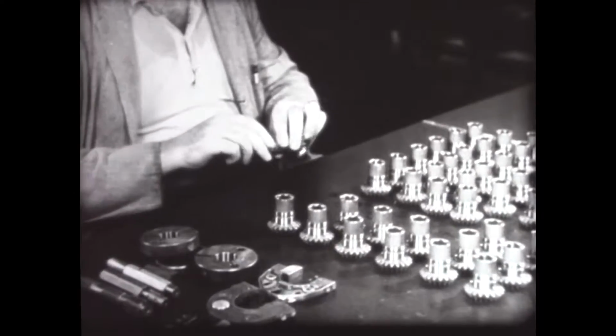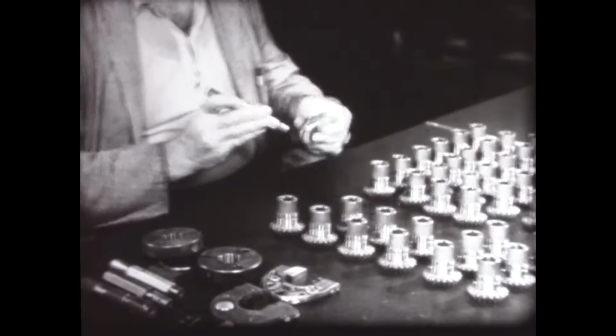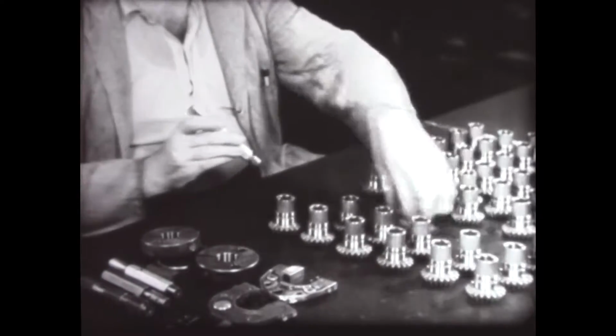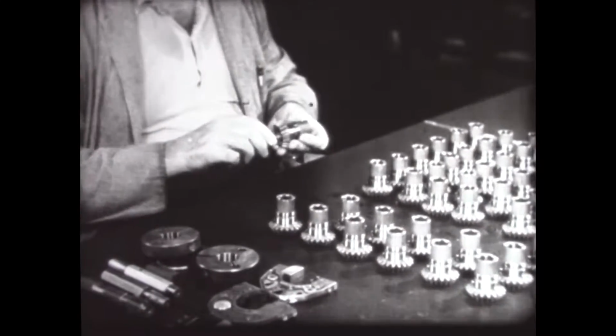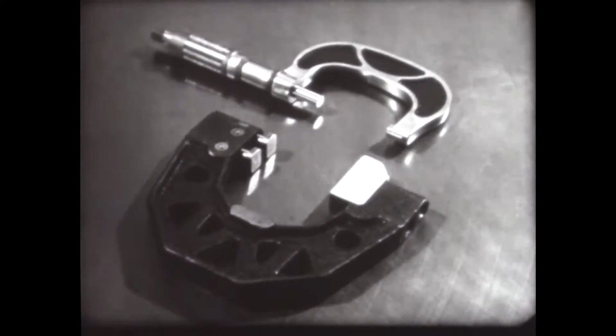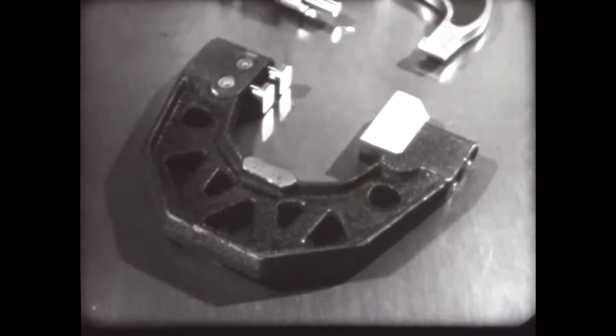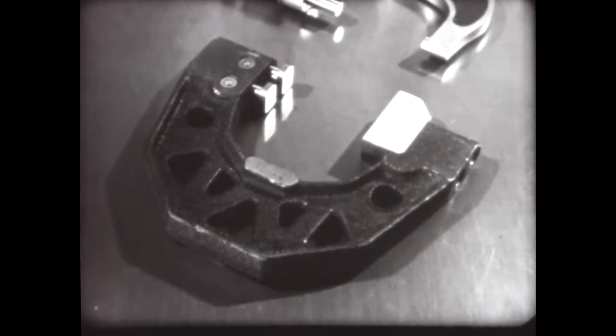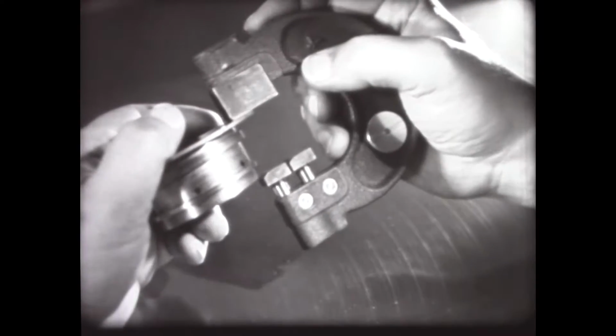For example, this inspector is gauging mass-produced parts that will go into airplane engines using special gauges made specifically to the limits allowed for each part. Most of the measuring tools used in mass production are fixed gauges. Fixed gauges differ from other measuring instruments, such as the micrometer caliper, in that a fixed gauge is not adjustable while in use. Some fixed gauges, such as this snap gauge, can be adjusted within a narrow range of settings, but the settings made remain fixed.